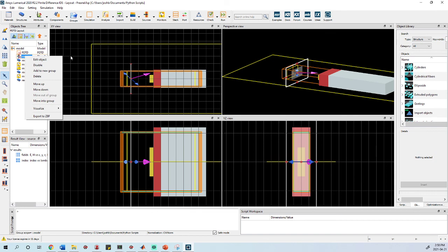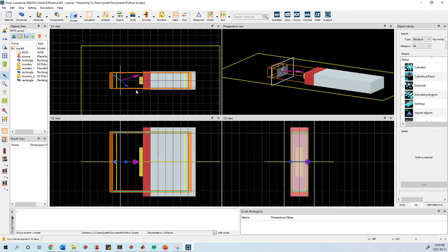What Bloch boundary conditions do is make all of your fields complex. Because, again, inputting light at an angle using real-valued fields with periodic boundary conditions gives you causality problems. On one boundary, you need to know what's happening at the other boundary at a previous time step. But on this boundary, I need to know what's happening at this boundary at a future time step. We don't know the future. So that's what causes the problem, and the solution is using complex-valued fields.